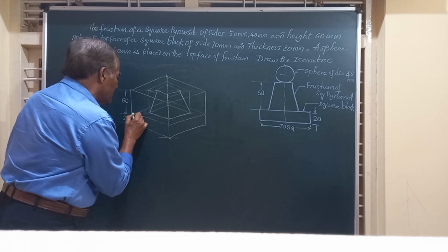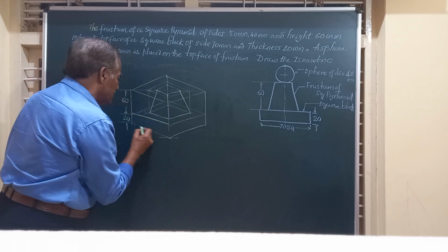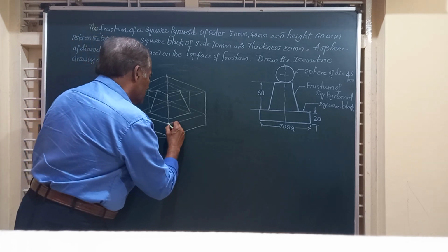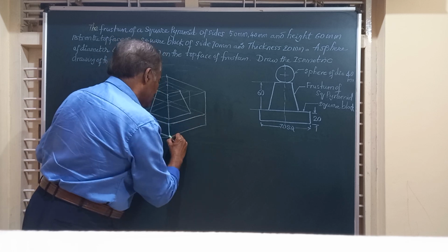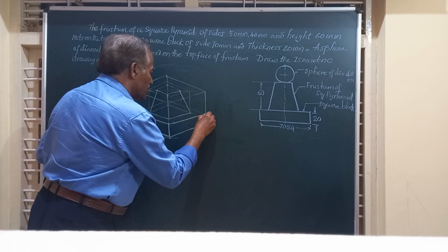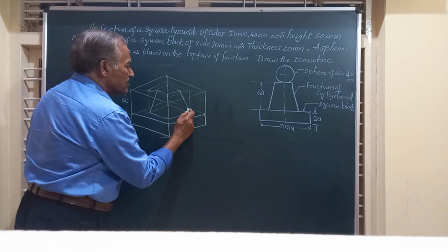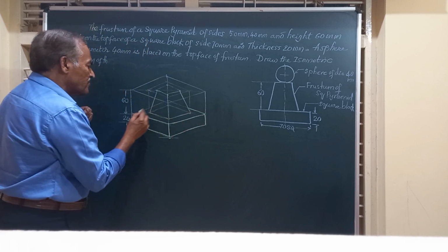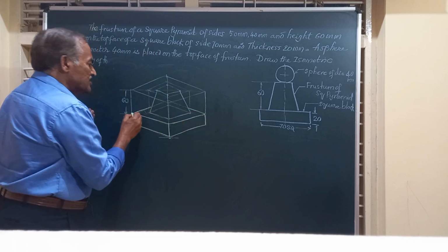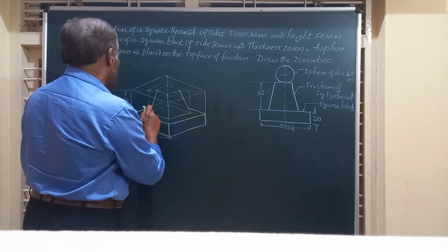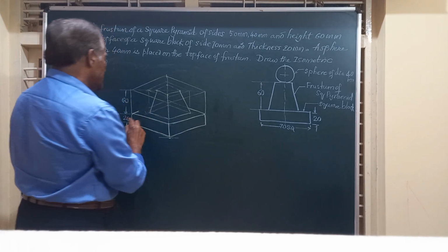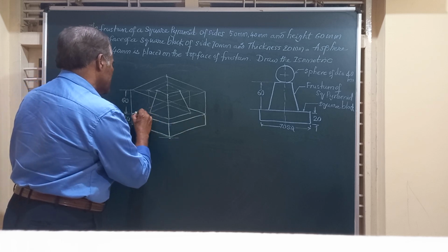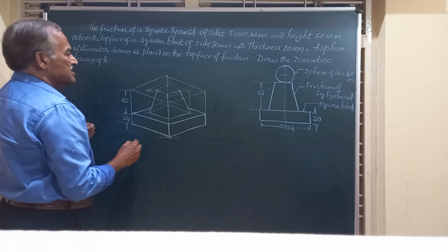So friends, I am going to join this line by a dark line, this by a dark line, this vertical line, a visible line here, then this line, visible line, line parallel to that, a vertical line. And friends, here, this has to be drawn till here. So that is the top face of the square block we have got here. This is the top surface of the block parallel to this. So probably it will be like this.